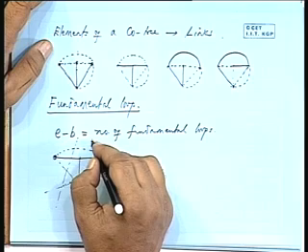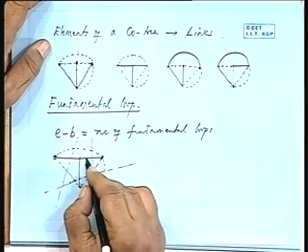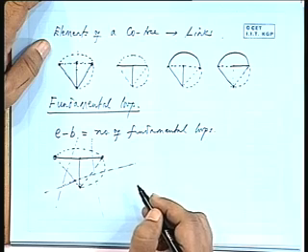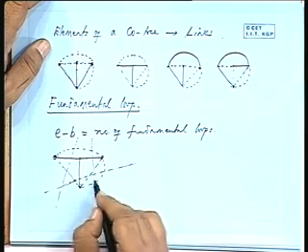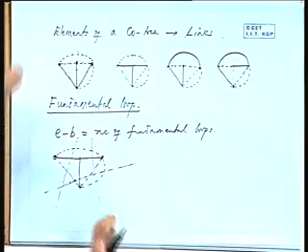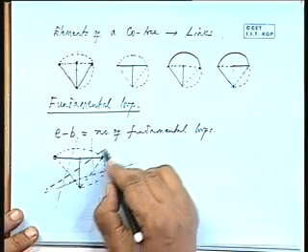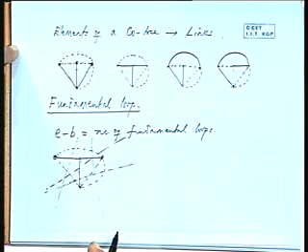I can cut along this, this is a third fundamental cut set, that is I am cutting this edge of the tree, I am cutting this edge of the tree, I am cutting this edge of the tree, okay. So you segregate the 2 parts by cutting one branch of the tree at a time, okay. There can be many other cuts possible. I can have a cut like this, I can cut 2 branches, that is also a cut set, but that will not be a fundamental cut set, okay.